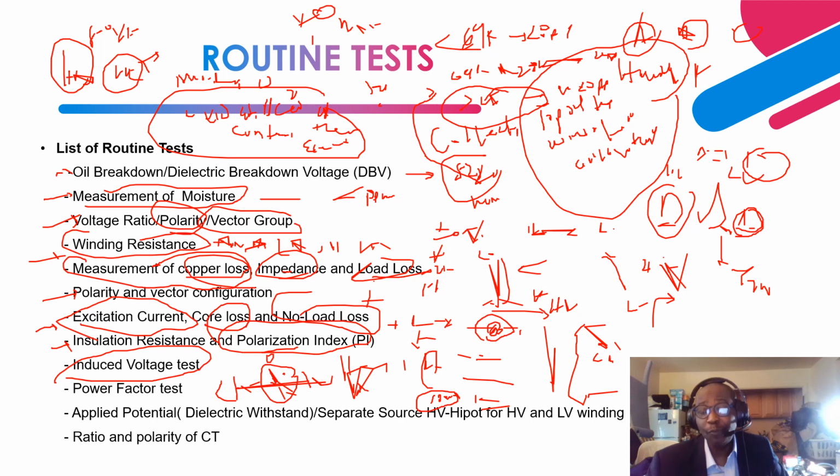For the low voltage side, if it is rated at 480 volts, about 2.3 times this value gives you the voltage that you need to apply, with the high voltage side floating. Likewise, if you have a 13.8 kV high voltage side, it's about 2.3 times that value, applied with the low voltage floating.